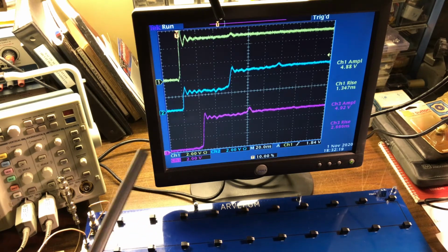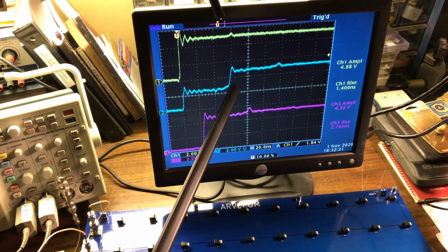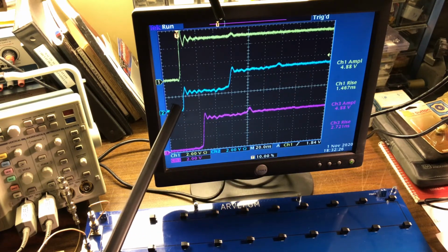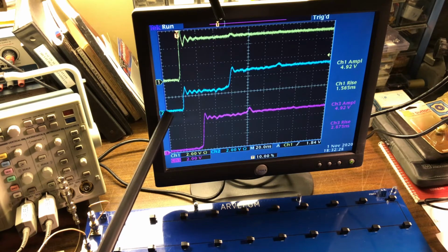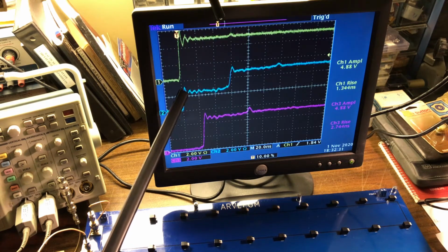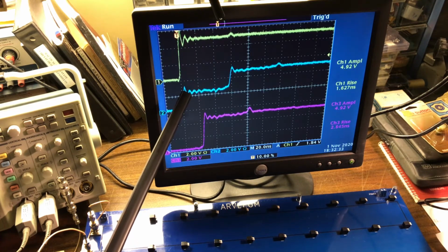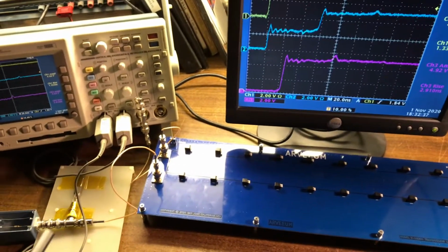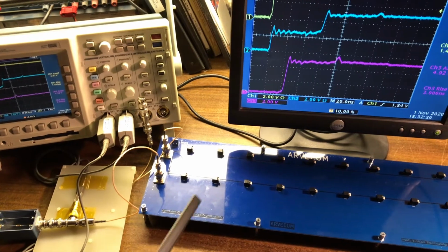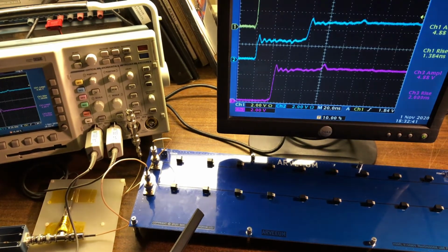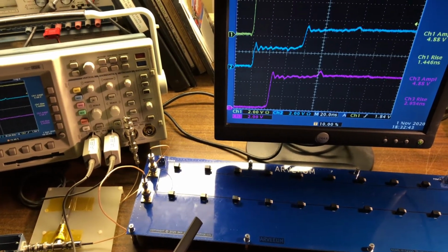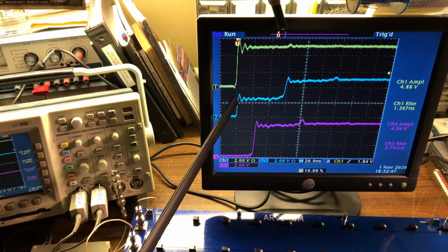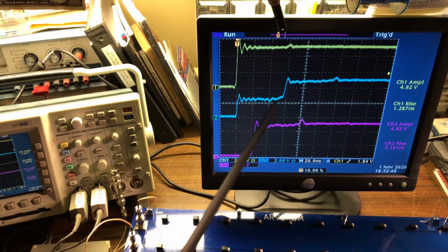You can see that at the input of the board, I can see the waveform that I should expect to see for a source terminated signal. I rise here, I go to half voltage because I have the 50 ohms of the source termination right here, and the 50 ohms of the first section of microstrip. So that's a divider, and so it's 2.5 volts here.